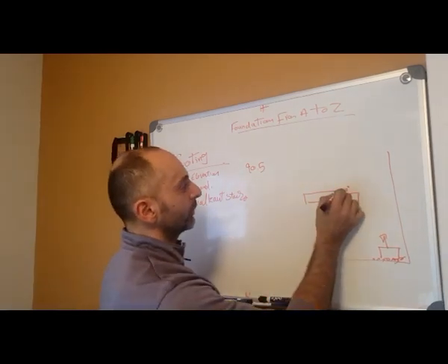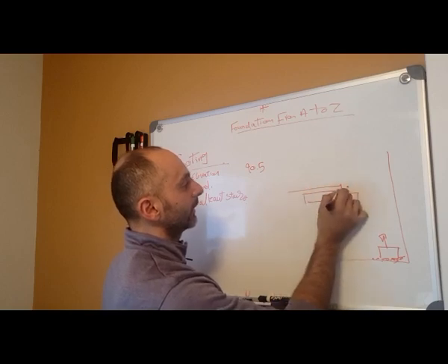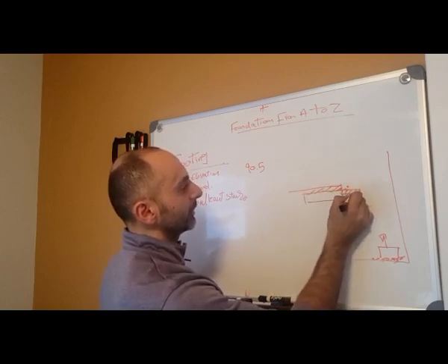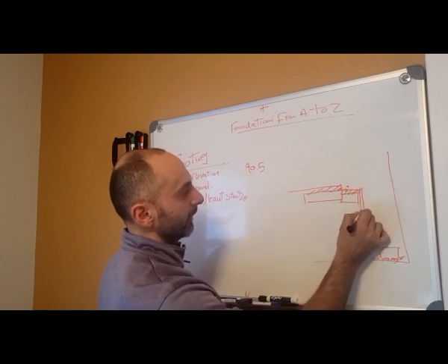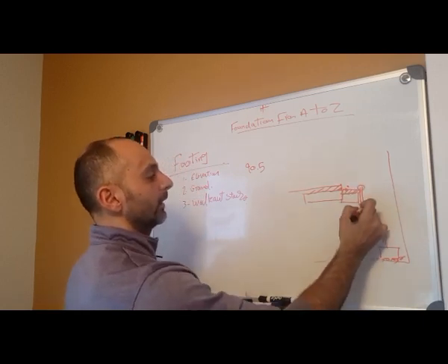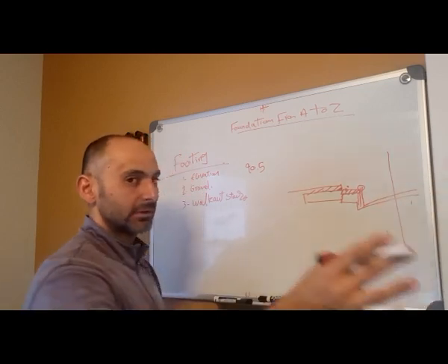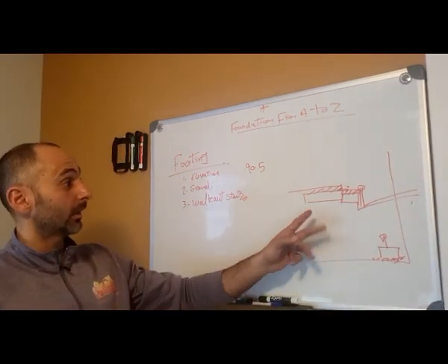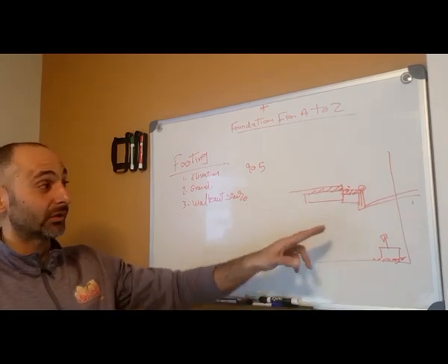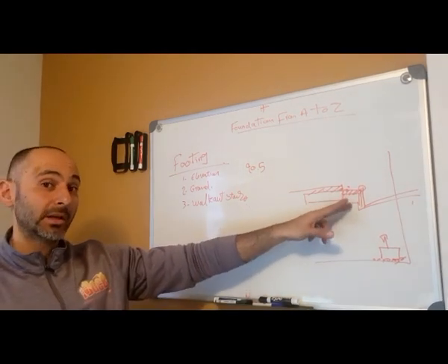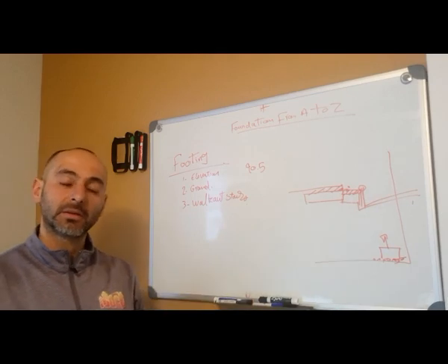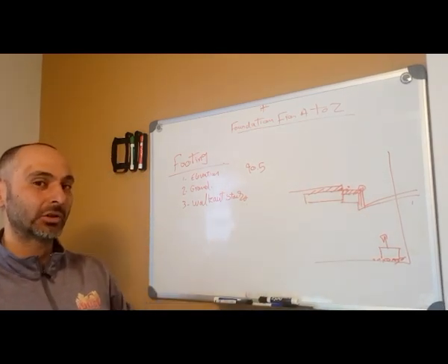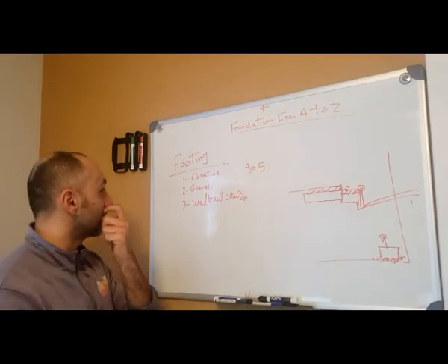So when you put your slab here, you maintain this 4 inches, and you run your pipe right there, you drain, then you take your drain out to the sewage tank or the stormwater drain. So make sure you get this right. It's a small detail, but if he's pouring on the same day, make sure your walkout footing is lower than the basement footing.